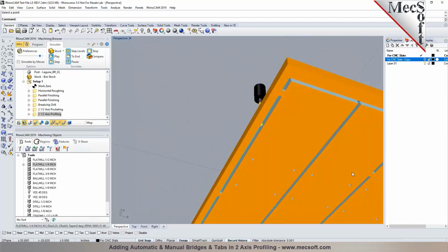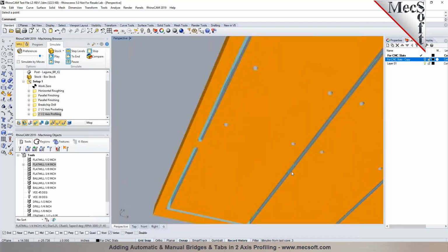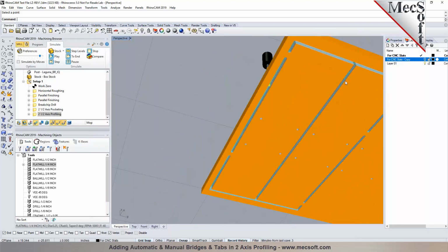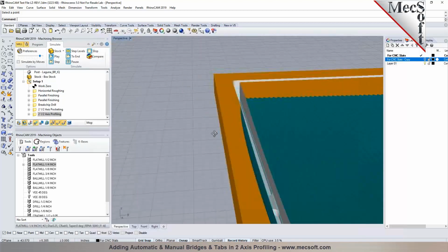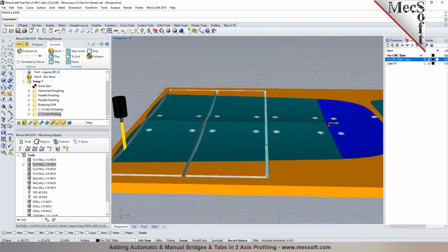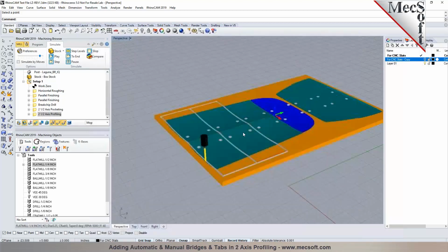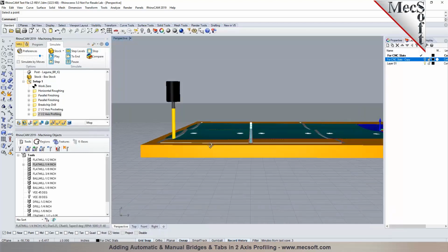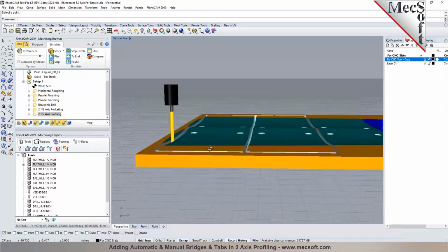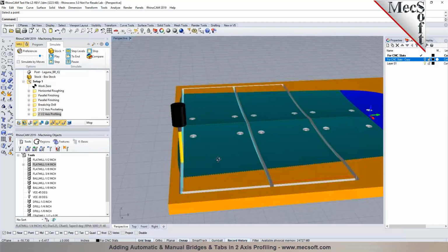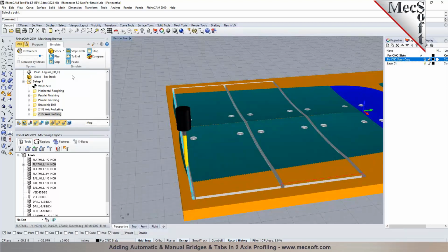In this case, since you have the parts that are so close, having the tabs in here is not going to have any effect because it's being chopped off with the other operation. So it's actually sending the tool, in this case, twice through that middle point. Yes, that is correct. And so what I ended up doing, I would draw this differently, is I selected all the odd slats, and then I just did the sides of the other 2 just to save on machining time. You could do that.